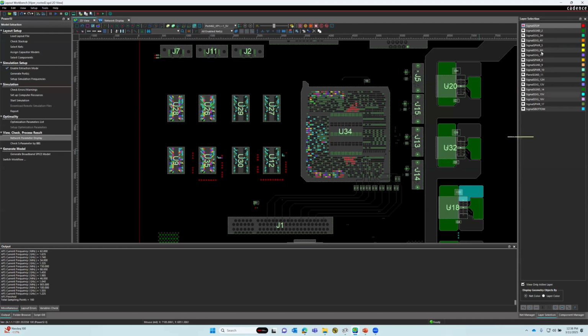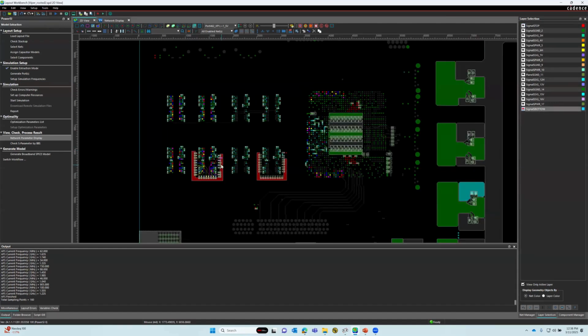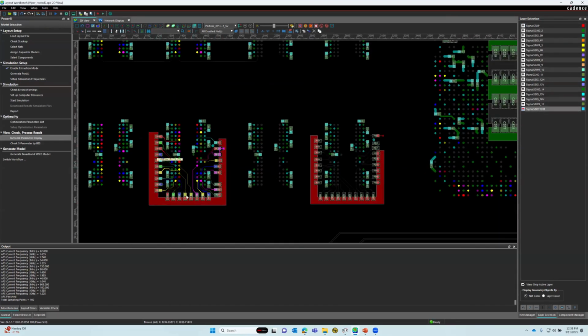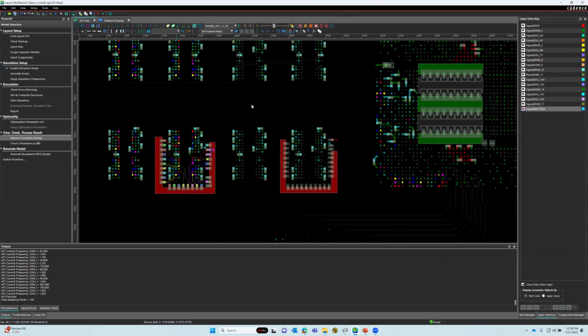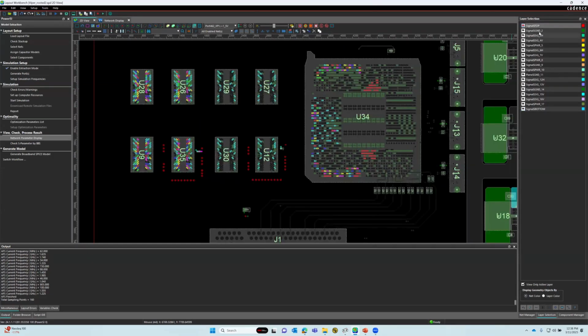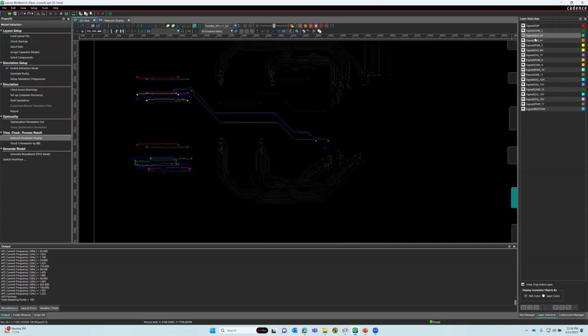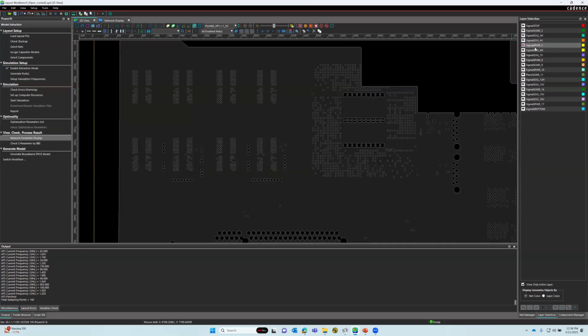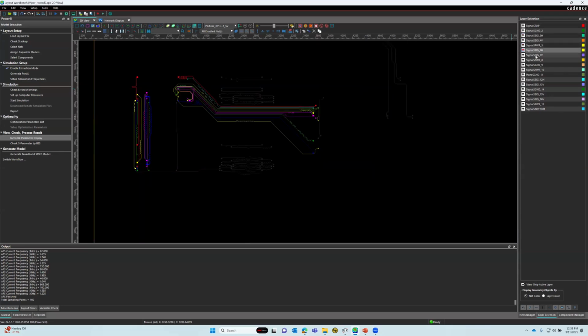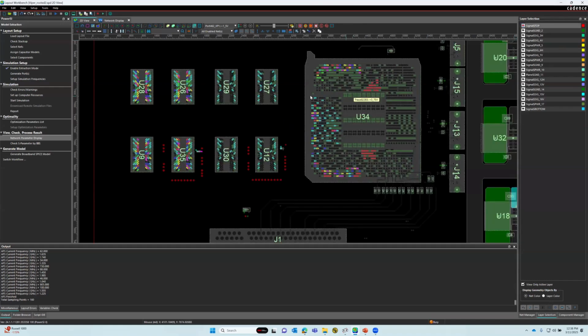You can see it's inclusive of the resistor terminations for the address network on the last one in the chain, as well as some of the specific layers that have the routing, and you can see how that routing ended up going there. So this is what I'm going to focus on setting up and doing a signal integrity check on, to make sure my signal flows are good. Starting here just gives you a lay of the land of where I'm going.